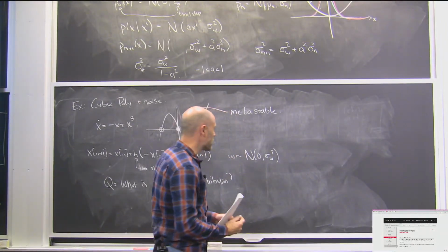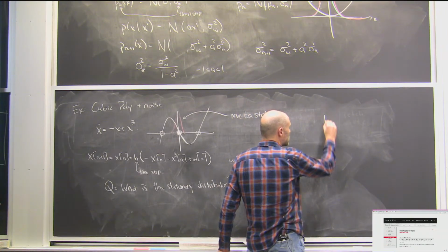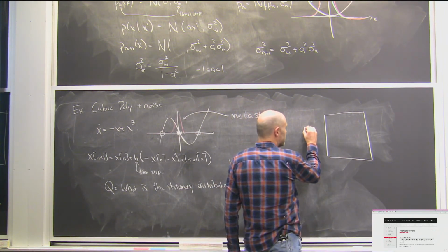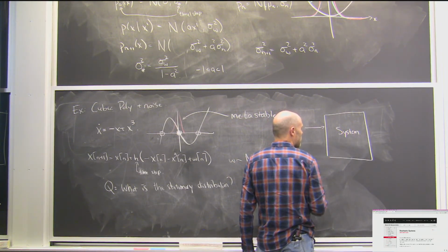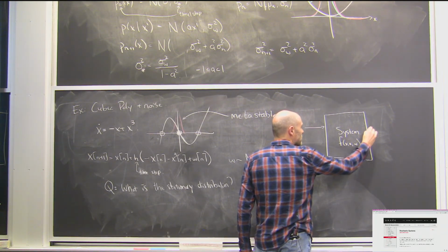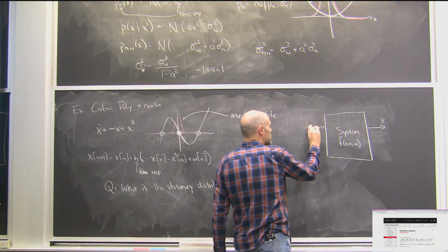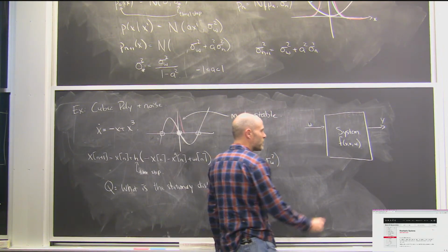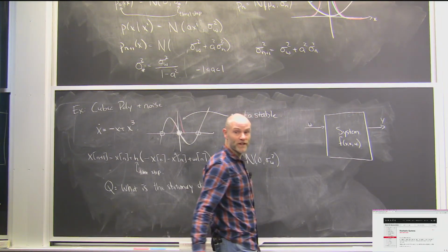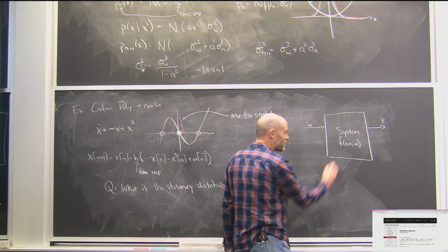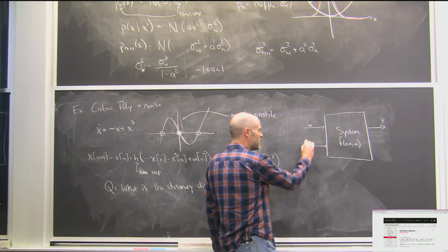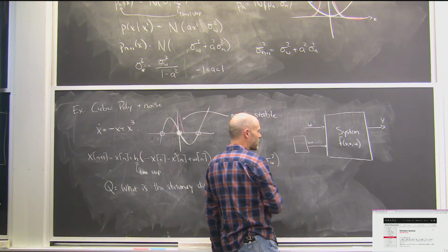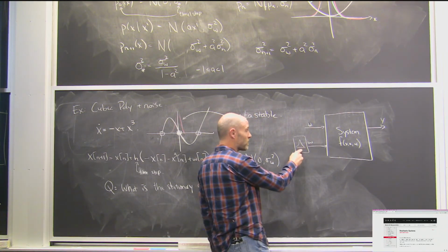Okay, quick aside. Since some of you are using this for your projects, there's a strong philosophy, I guess, that I tried to be very careful about in Drake: how we model stochasticity. Again, systems are f of x, u, but potentially w, and we can have outputs y, inputs u, for instance. When you write a system in Drake, certainly all the systems that are in Drake proper, that system is never allowed to call a random number generator. Not allowed. You've broken a rule. If you want to have a stochastic system, you must add an additional port, W, a random port, and then there are some tools to make it automatically introduce a random variable input.